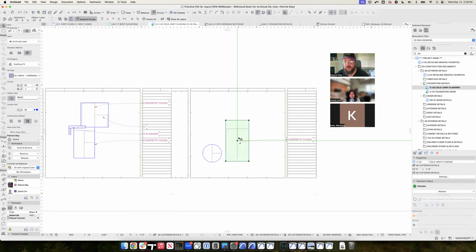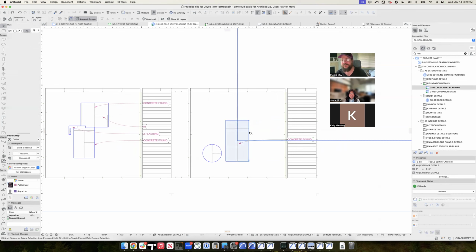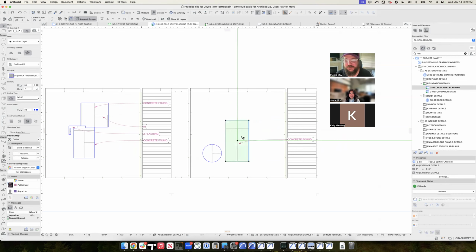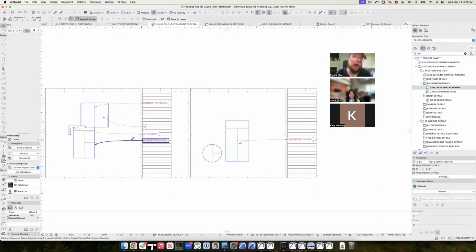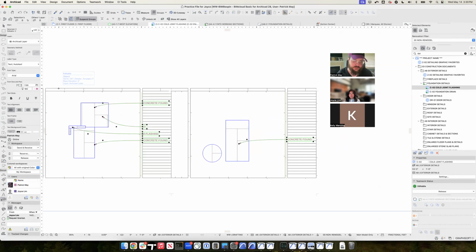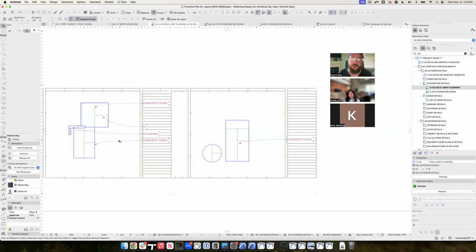On this one, I want it to associate to this one. So I'll select that dimension and surprise, surprise, command click is the key for that. Command click is really a catch-all for a lot of things in ArchiCAD. And now that thing is associated to this one. If you wanted to grab all of your details and disassociate them, you can grab your label tool, hit Command A and cut them out and paste them back in, and now they're no longer associated to anything.